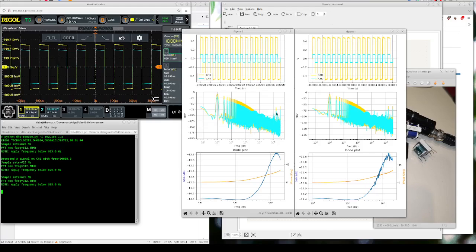But this part is all noise, and it's not interesting because this transformer cannot go any further than, well, 1 megahertz is still fine, 2 megahertz, and then it starts to resonate here. So I think for the open loop gain, which I want to measure for my opamp, 1 megahertz should be doable. So that's why I tried this transformer.